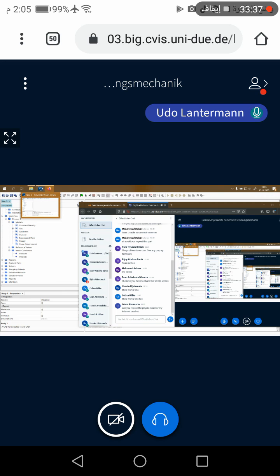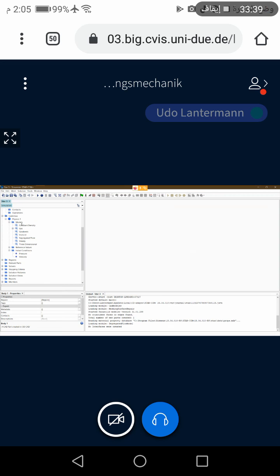Okay. Physics models. So again, I can show also here. Click with the right mouse button on the models and then select models. And then you have to choose constant density, gas as fluid, inviscid in the viscosity, segregated flow in the solver, and three-dimensional.